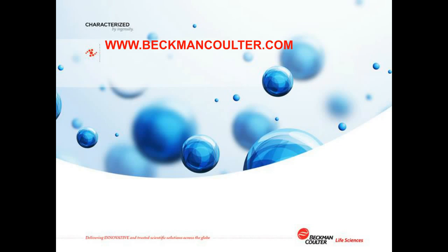But I've seen sites just this year which were using particle counters that were made obsolete 20 years ago, and they're desperately hanging on to them because they don't want to change them. But unfortunately, because they are so old and they're producing just a paper printout, the actual computing engine, if you like, inside those particle counters is not capable of generating an electronic record. It's just not powerful enough. So there's nothing much you can do with them, I'm afraid, other than buy the next generation from your supplier, which hopefully would allow you to put the electronic SOPs in there and generate the electronic records.